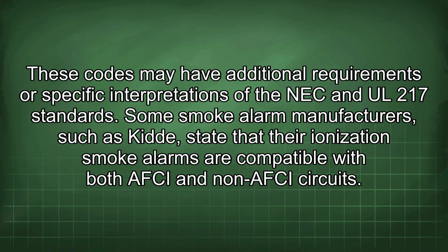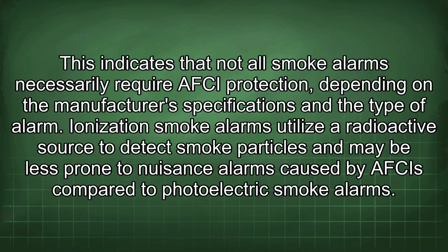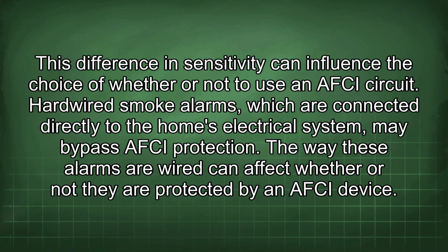Some smoke alarm manufacturers, such as KID, state that their ionization smoke alarms are compatible with both AFCI and non-AFCI circuits. This indicates that not all smoke alarms necessarily require AFCI protection, depending on the manufacturer's specifications and the type of alarm. Ionization smoke alarms utilize a radioactive source to detect smoke particles and may be less prone to nuisance alarms caused by AFCIs compared to photoelectric smoke alarms. This difference in sensitivity can influence the choice of whether or not to use an AFCI circuit.